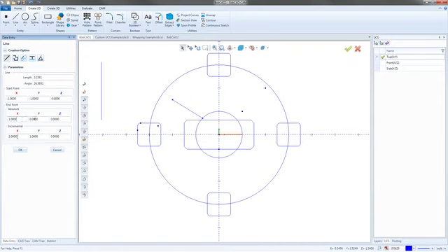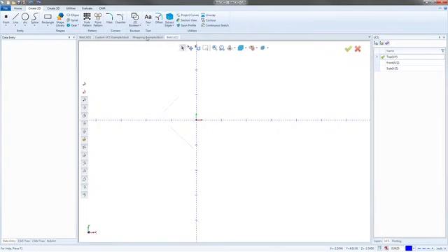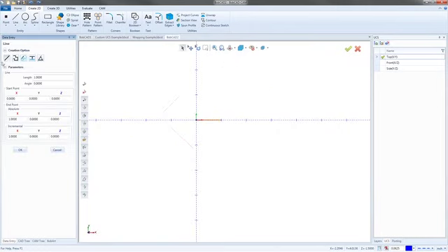And so now what we'll see is the increment. I don't know why my preview's not popping up, but now the increment is going to get me to x1, y0. It's got to go 2 inches in X and 1 inch in Y incrementally from where we start. And if I hit OK, it'll pop up, but my preview is not showing up. I don't think I turned anything off. I'll probably need a restart, but there we go. So that's the line sketch kind of functionality.